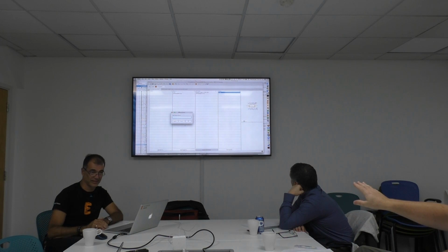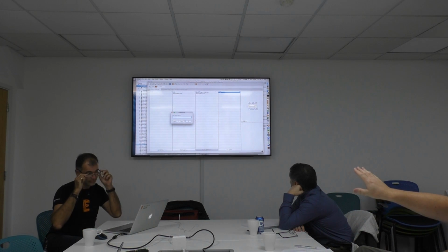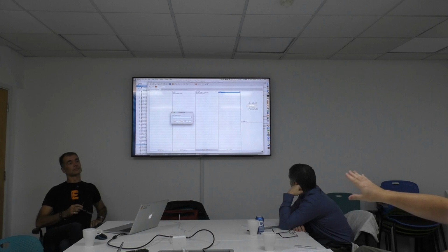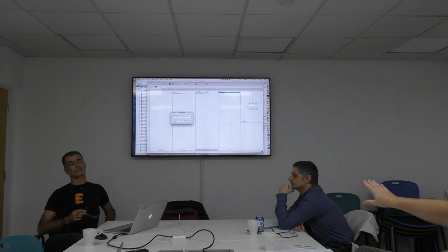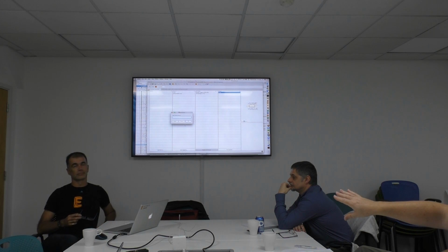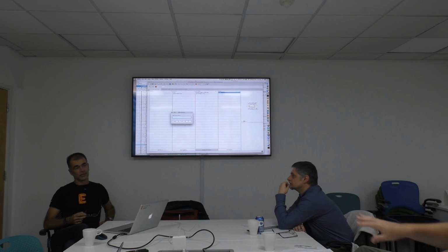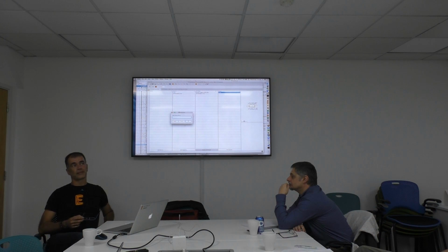Is this the preferred sequence? So you do your package footprint, symbol, and then add device as the last stage? That's my preferred way. Yes. Once you have the other bits done, the last step would be to create the device.